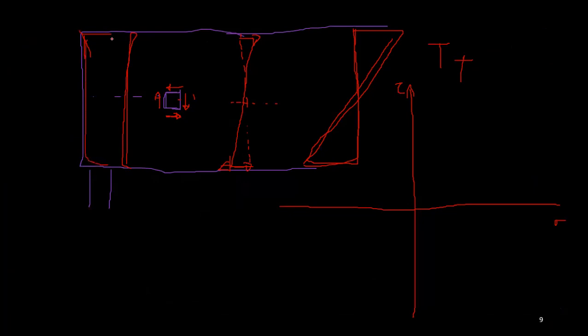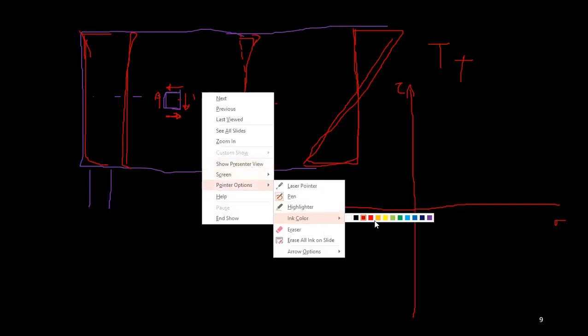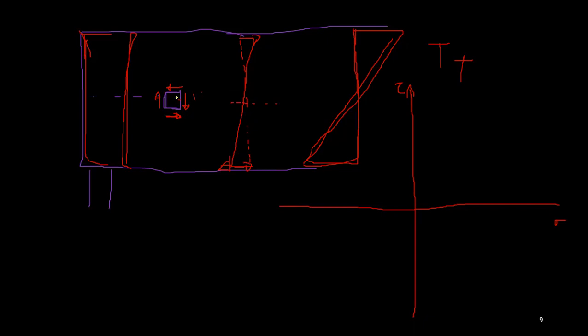Usually we take the average shear, right? But if you consider maximum shear stress distribution, here I did not draw any distribution because the average shear is something and the maximum shear stress is the actual, right? That's why we take some element close to this support where the shear is at maximum, right?